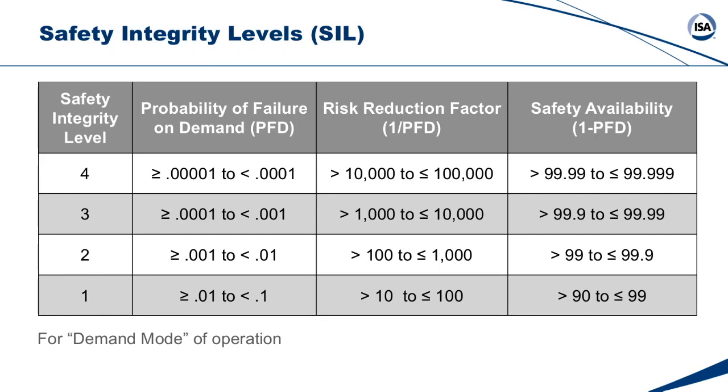It's like, please. I mean, if you factor in people, you won't even come close to that, and maintenance issues and everything else. It's much more than just analyzing the probability of device failure. There's a whole lot more that's involved with all these numbers. It's more than just statistical number crunching. I know people in the process industries and the refining industry who say they don't even have any SIL 3. Just because they may have high risk doesn't mean you have high safety integrity level requirements. Think of all the other multiple independent protection layers you have, and doing an appropriate SIL selection review, that you should not really have even SIL 3 requirements.